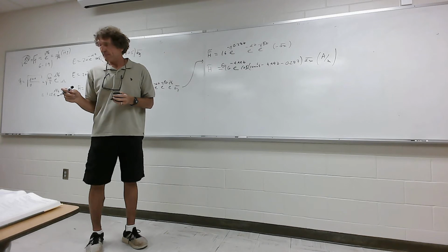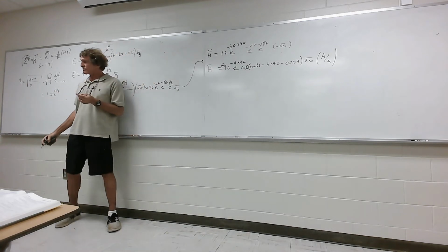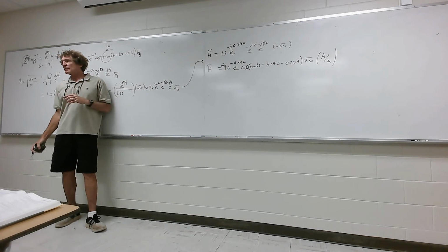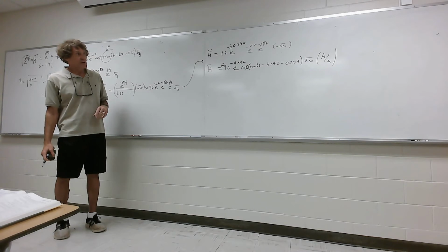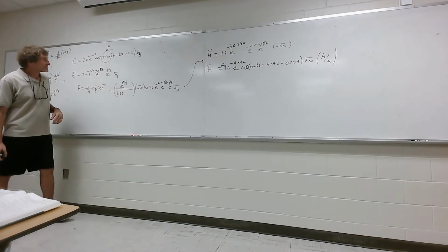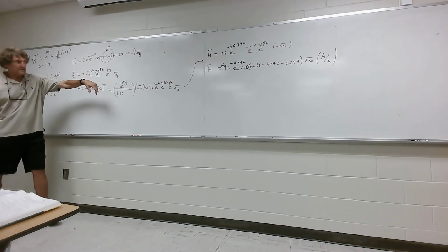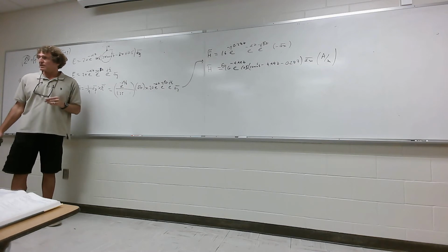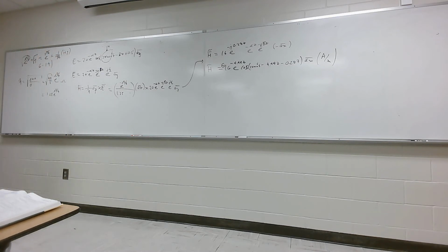Yes. Okay. Take a look at it. You asked it, you see what went on there? Most of the time, the things that cause you strife or some kind of concern is you're not sure a lot of times if you can get some of these quantities just by looking at this. Well, you can't. The only way you can get them is doing the calculation, getting gamma equal to alpha plus j beta. How come the e to the minus 4.44 z is outside the cosine? Because that's strictly real, isn't it?